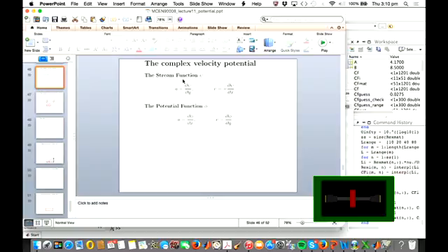So in this situation, we're generating a huge amount of drag and only generating maybe twice as much lift. So the lift to drag ratio is terrible. So that means that if you had an aircraft that weighs 10 tons, you need to generate 5 tons of thrust. Yeah, that's horrible. Yeah. So I mean, when it's 1-to-1, you're back to being like a ballistic rocket. I think you don't even have to do all the factors.